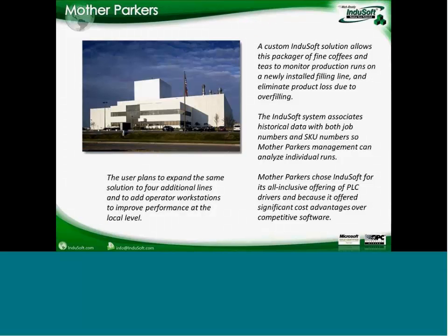In addition to that, there is a central server running InduSoft Web Studio as well, collecting data from all the 17 lines and saving this information to a database, working as a portal for thin clients where they can get online data or history data and reports with information about the production.